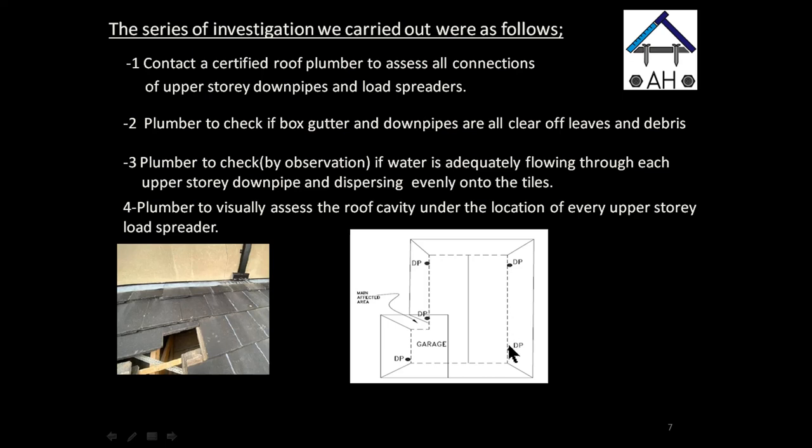the entire residence. The issue in the garage was that the ceiling plasterboard cracked because, number one, it was wet due to water seeping in that cavity, but in addition to that, it was carrying a wet insulation as well, and that put an additional load on that. And you can refer back to the video in part 1. We spoke a little bit about that.